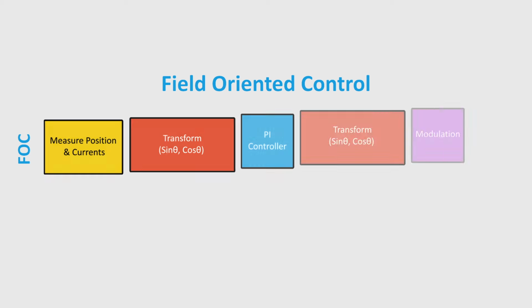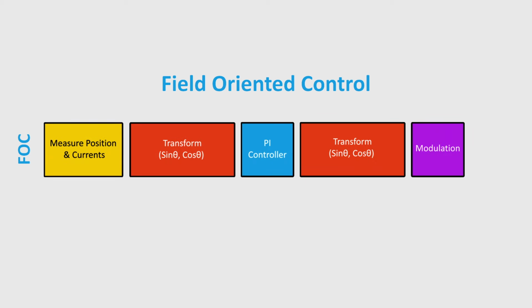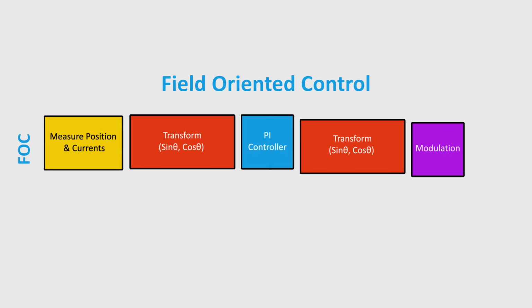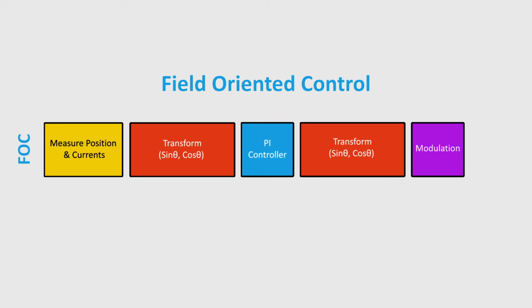Motor control algorithms can be thought of as sequential procedures. You follow a defined set of steps which you can't skip or remove. These steps in turn define the execution time, which in this case for field-oriented control is 8.24 microseconds. The motor speed defines the window in which you must perform these calculations, but the problem is that in the most commonly used approach, field-oriented control, the entire window is taken up. Therefore, you can't make your machine faster and your powertrain smaller than this processing limit allows.